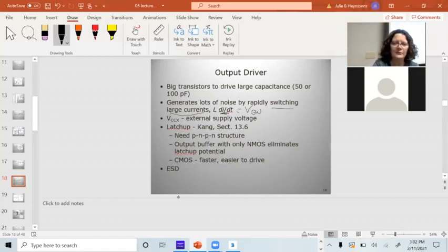I have a separate external voltage supply. I do not want the crazy PCB designers having any contact with my holy VCC supply that's going all over the chip. I want them to have a separate power supply to run those pins. So if the board designer is giving me really noisy signals, those noise signals do not propagate into my IC, because I don't want to have to deal with that.